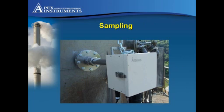A typical view of sampling underway from the source. Normally, the probe enters via a 4-inch or 6-inch flange. Here we see the illustration of the probe into the stack gas showing the cam-lock quick release technique for inserting and removing the probe.